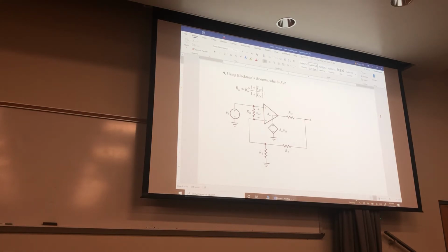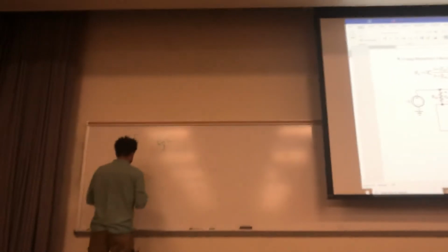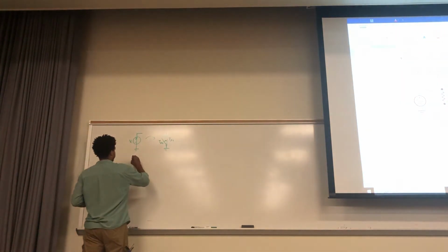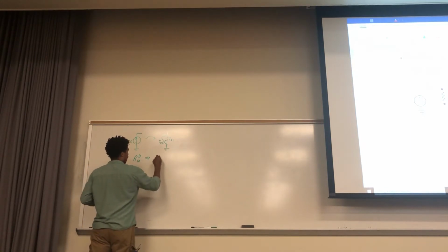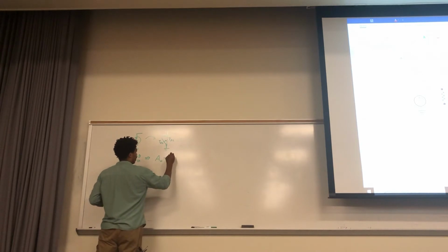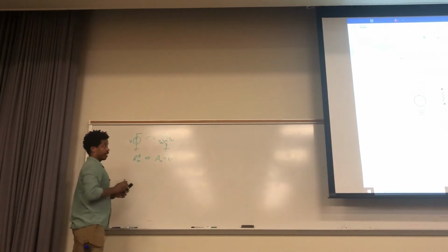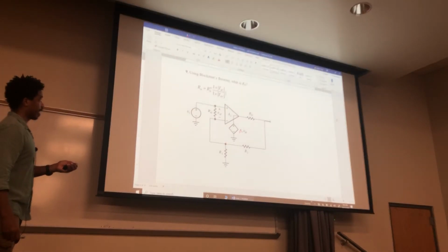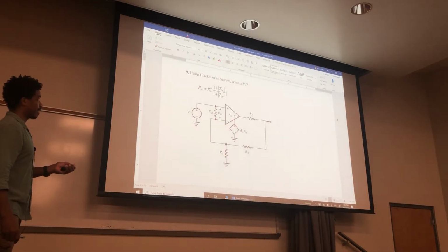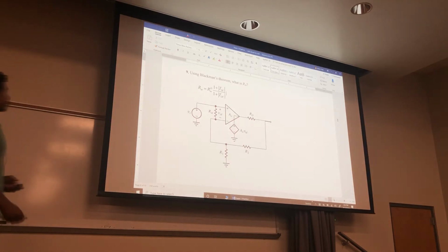Okay, so now for RIND, that implies that you're turning off this voltage controlled voltage source right here. So that's going to be 0. Think of that as a short circuit. Not an open circuit, a short circuit when the voltages are off.